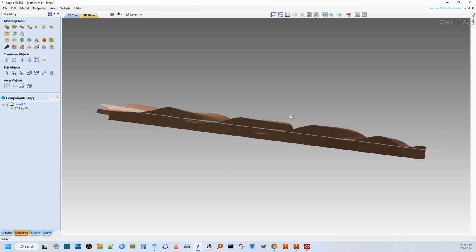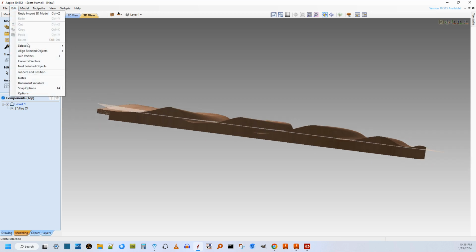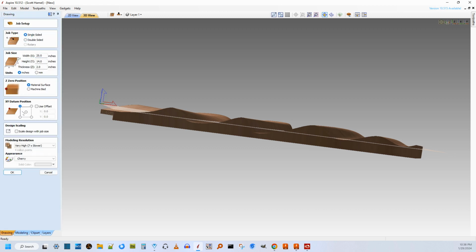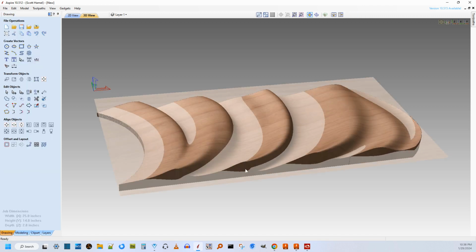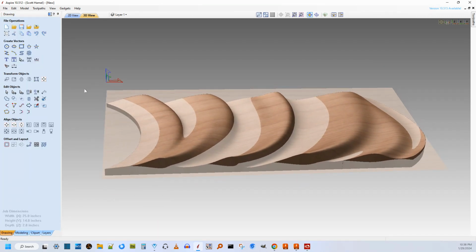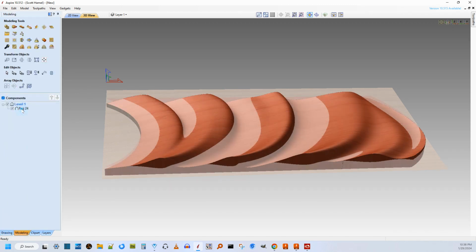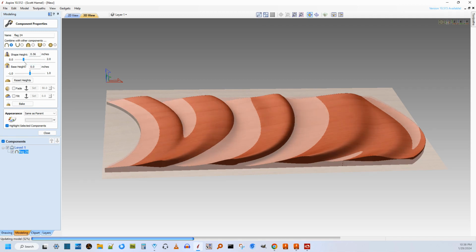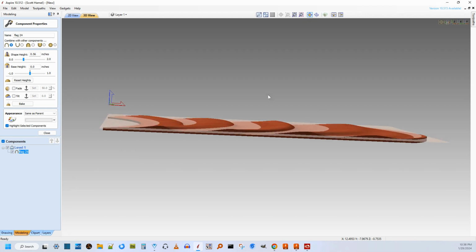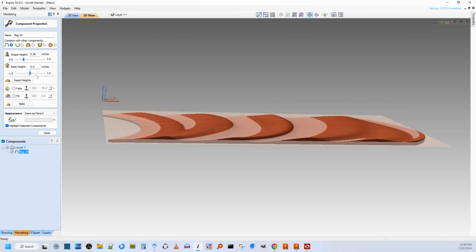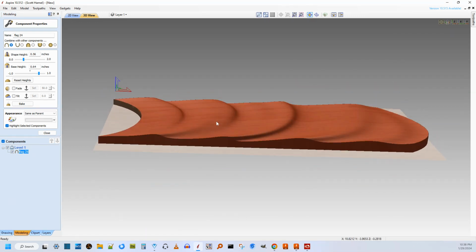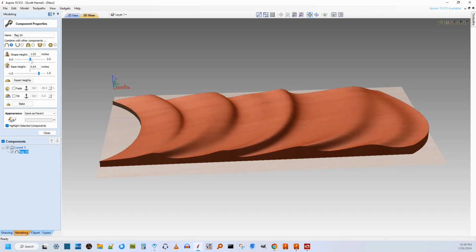Looks pretty big. Oh, we must edit job size and position. We don't want double side. We want single side. And hit OK. And that model height is a little bit big. So an easy way to fix that is just go here, flag, double click, and just reduce this height. And if I get it real skinny, you won't hardly even see it. But I can, and if I want a bigger base, I can just add the base to it. So it looks like that. So whatever you want to do. That's the cool thing about these two tools. They interact with each other pretty good.